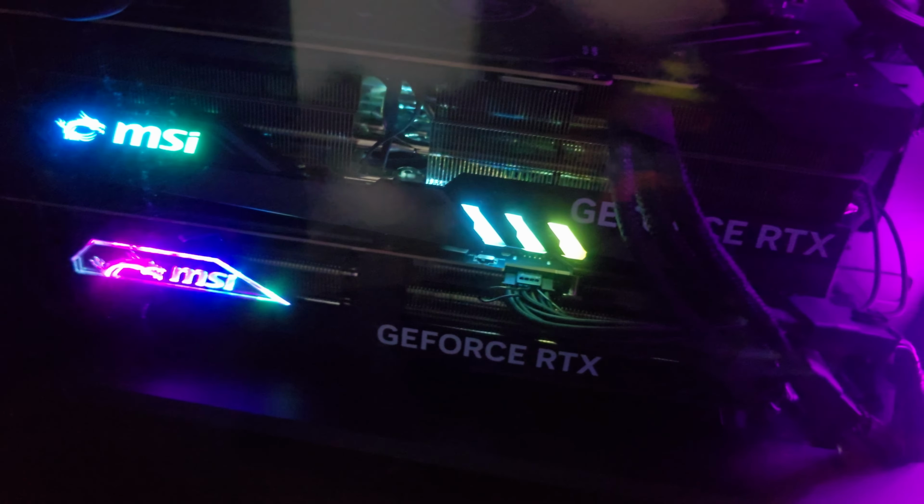This motherboard also supports up to a massive 2 terabytes of DDR5 ECC RDIMMs across its 8 slots, and it is 1 DIMM per slot, which means you get a ton of memory bandwidth. Theoretically, with 4800 megahertz of RAM and 1 DIMM per slot, you get about 307 gigabytes per second of memory bandwidth. Yes, that's theoretical and we don't achieve that much, but that's the theoretical number that you can get with this.